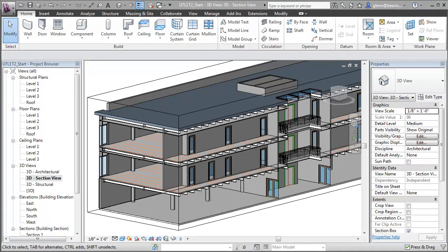While the convenience of using these multi-layer elements works very well for design modeling, it starts to break down a bit when we consider using BIM models for construction modeling. In particular, treating all of the layers as a single element creates inaccuracies for construction planning because the layers of the wall won't be assembled as a single unit.